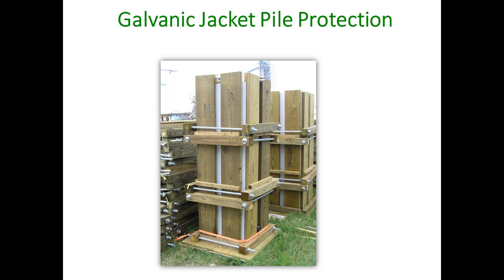And so they're installed around a pile. There's a number of different methods and ways you can do it, just depending on how the contractor wants to do it. But it's a fiberglass form, so it can be a square jacket, it can be a round jacket, and you're going to need some sort of bracing or some sort of support, and then you're going to pump this jacket. You're going to fill it up with grout, with just a standard concrete grout.